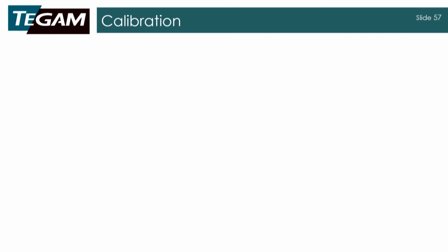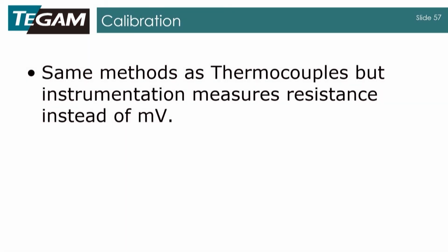And then to calibrate these, it's going to be the same methods as we saw for thermocouples, but your instrumentation is going to measure resistance instead of millivoltage.